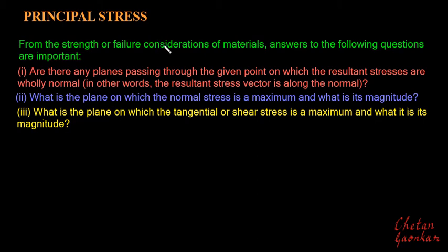So after looking at concepts like state of stress at a point and Cauchy stress formula, let us discuss now on this topic principal stresses. Now we know from our elementary mechanics of solids knowledge that if a 1D bar is subjected to say point load P, which is fixed at one end, then since this is an assumed 1D bar subjected to only point load in one direction, we know that the principal planes will be exactly perpendicular to this applied load.